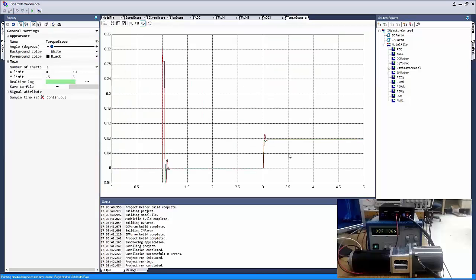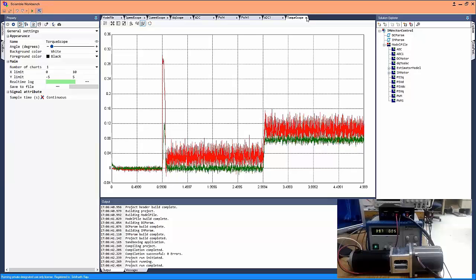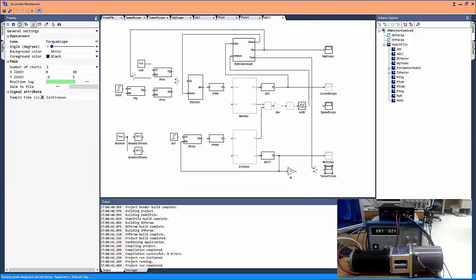Similarly, the torque result obtained in simulation, the electromagnetic torque, matches exactly with the load torque under steady state in simulation, but in reality there's going to be a discrepancy because of the viscous friction component. If we had modeled the viscous friction component in our simulation as well, we could have had similar performance in simulation for the mechanical system as well. So let's go back to the slides and continue from where we left off.